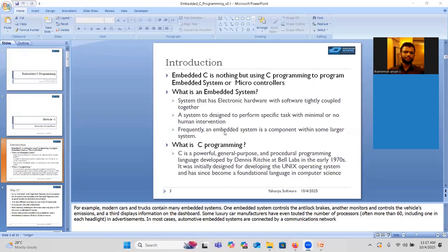Now, the embedded developer who develops the program for the speedo gauge will convert the input speed to the required PWM frequency for the stepper motor. Whenever there is a change in the speed, there will be a change in the PWM generated by the controller that is fed to the stepper motor as a control signal.